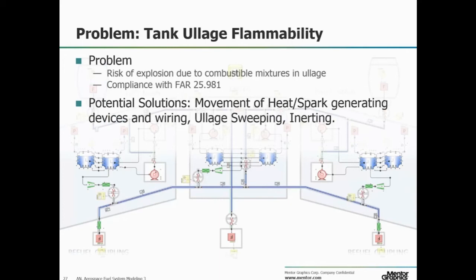Using multi-fluid simulation, along with the advanced tank component, we can now use Flowmaster to study inerting scenarios and ensure that our tank, vent, and inert gas generation systems are all properly sized and configured, helping to find a solution to a very serious aviation safety issue.